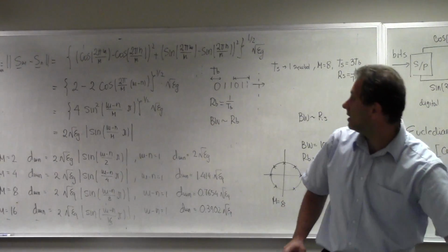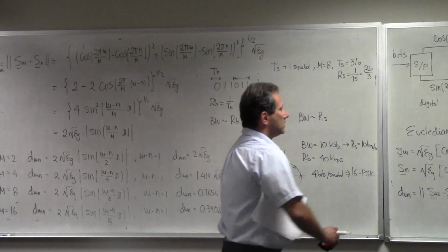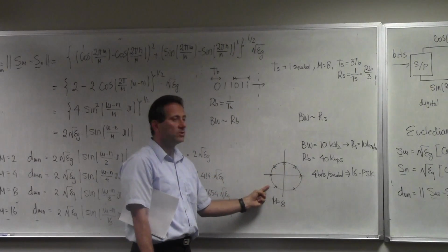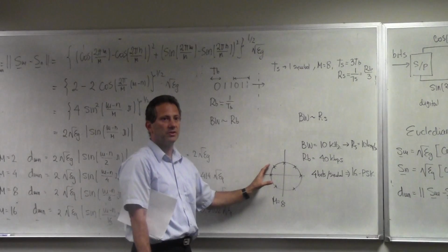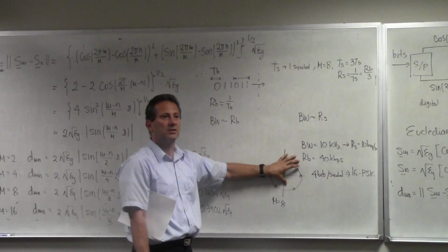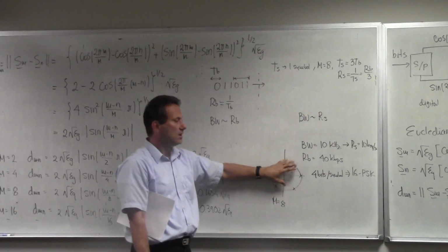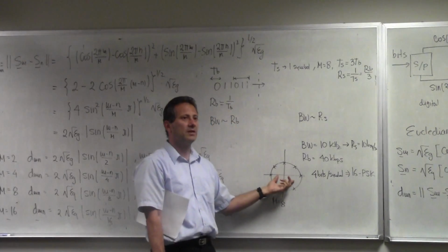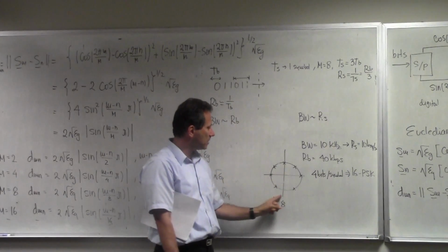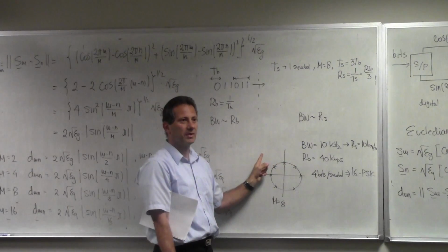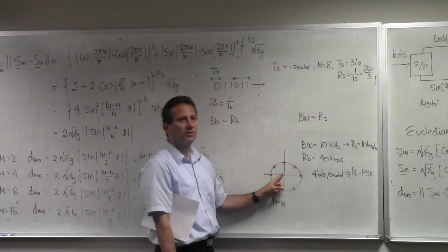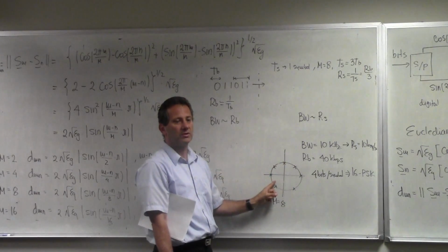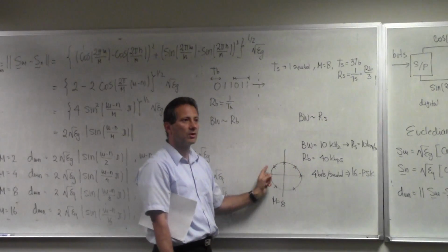So this is PSK. As I said, the key point about PSK is that all symbols are on a circle of the same energy. This makes it nice because the envelope of the signal is constant, and therefore the power of the signal is constant. But even from these preliminary considerations, you see that there's one fundamental flaw here: if I'm given this much area in my signal space, there's a better way to redistribute these points to maximize the distance between them, right? I don't want to jam them all on the same energy circle. I can actually spread them more in this space.